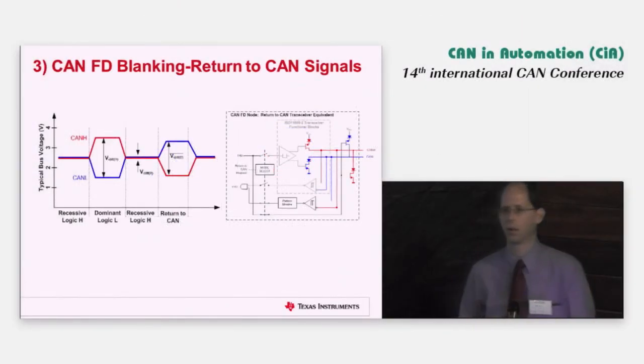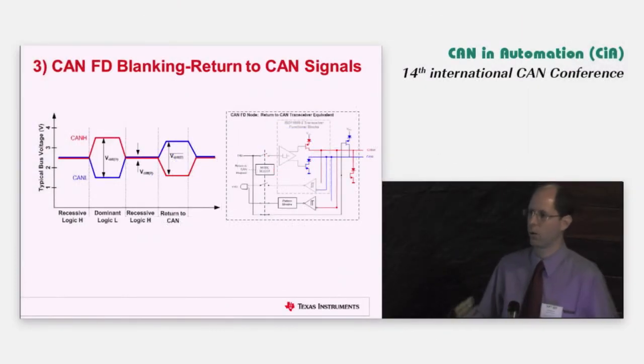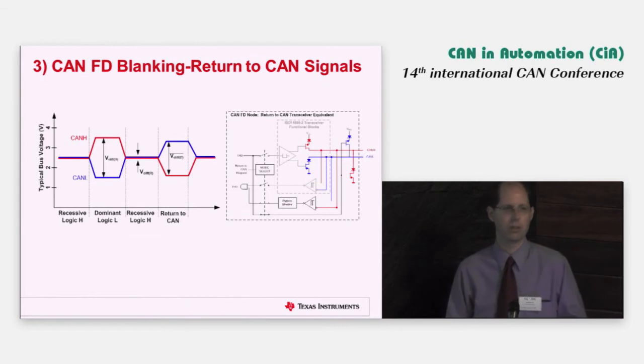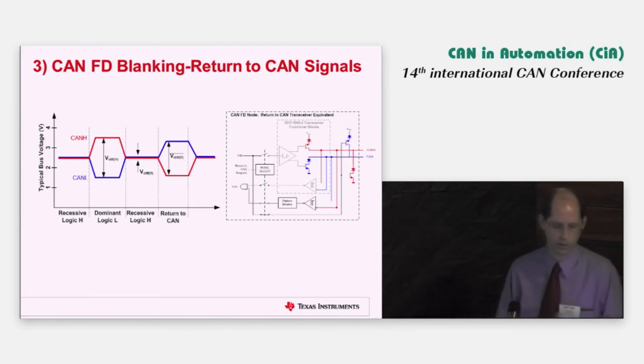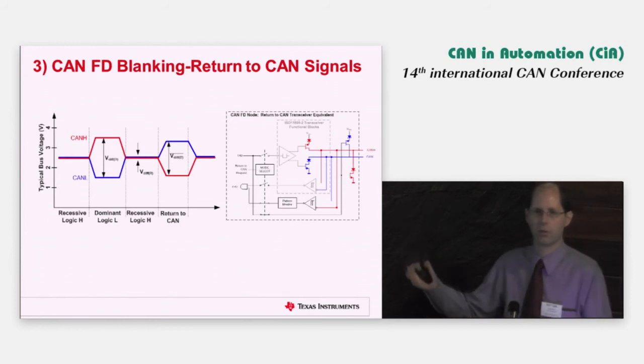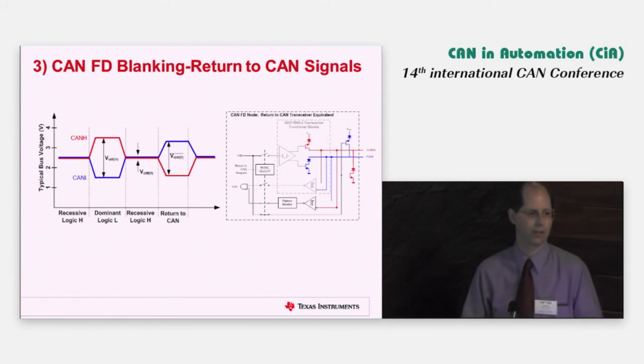Similar to Part 5 of the CAN standard, where the wake-up receiver requirements are relaxed versus the main receiver requirements, we could do a similar fashion here with the driver and the receiver, where we aren't trying to actually talk CAN FD time, nor are we trying to necessarily cover all possible systems like 1 kilometers of cable.